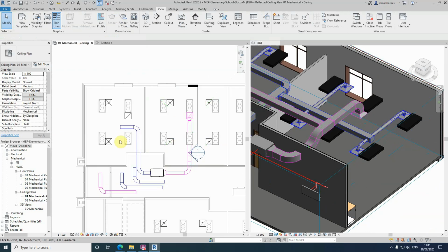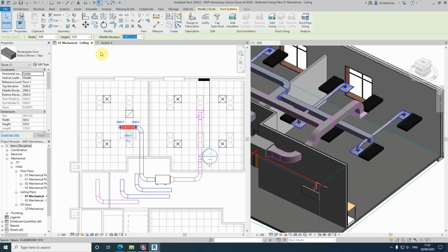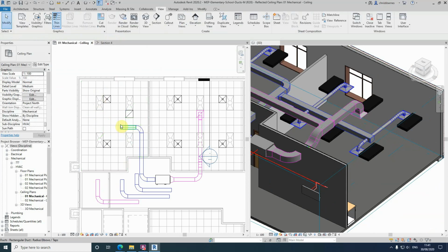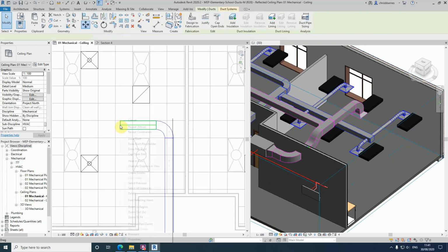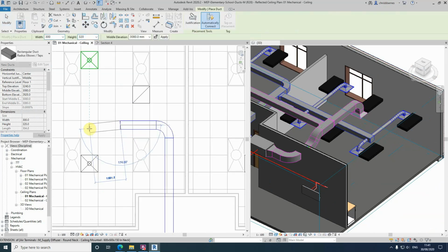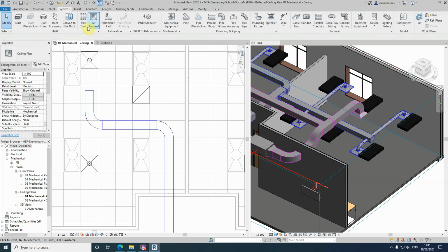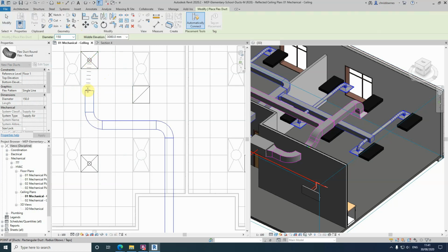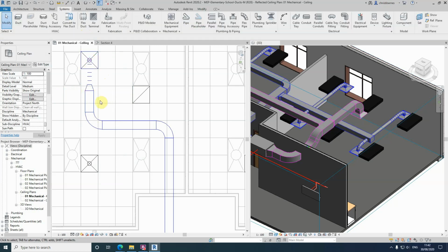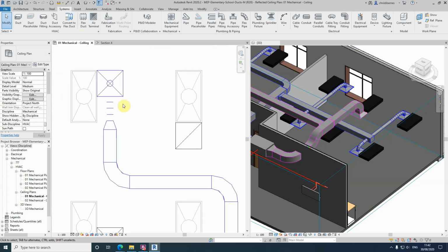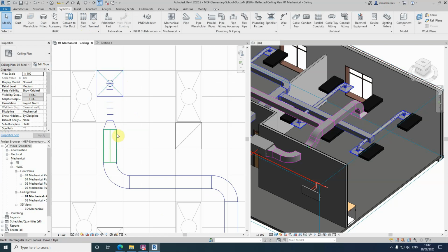If you're wanting to connect up and use FlexiDuct, lined up to here, I'd finish it off like so, and then in the systems, FlexiDuct, connect from that to our duct. As I say, connecting it from, just like we did, we started from the equipment such as the air handling unit here. What I did there was I connected from the grill and then connected to the duct.